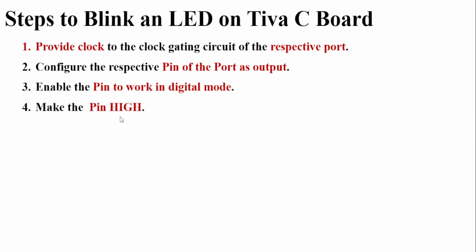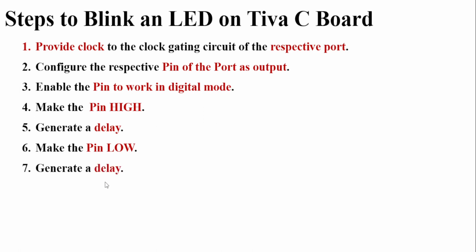Then we will have to make the pin high, generate a delay so that the pin will remain high for some time, and then make the pin low and then again generate a delay so that the pin will remain low for a certain time period.